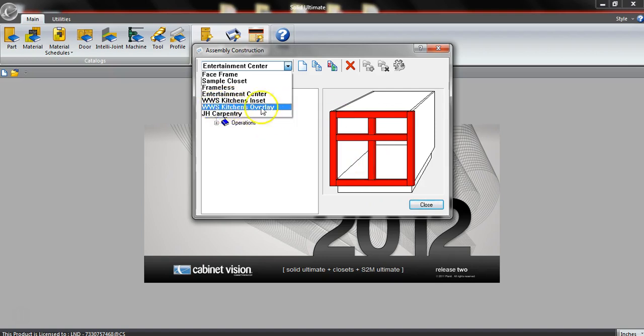The only difference is these mid rails are 1 5/8 because you want that 1/8 inch reveal when you have overlay doors and drawers. So I just go in here and pick whatever I'm doing for each job. Super nice, super easy. The hard part is, let me take you in here and just show you an example.